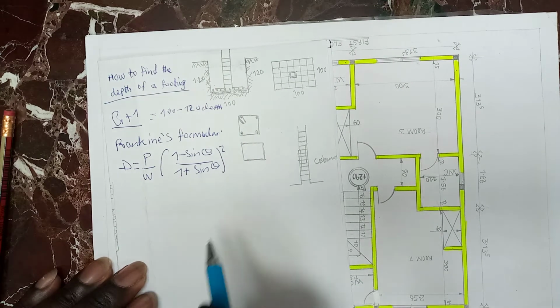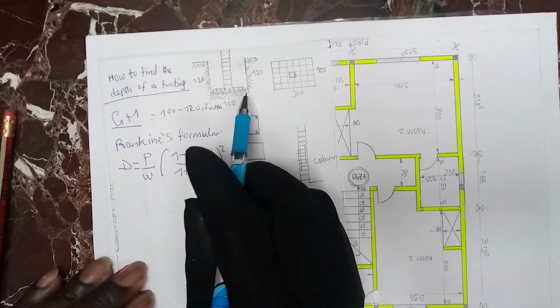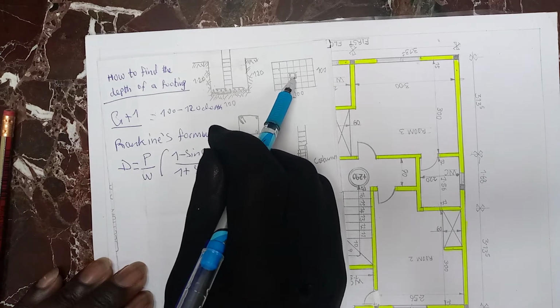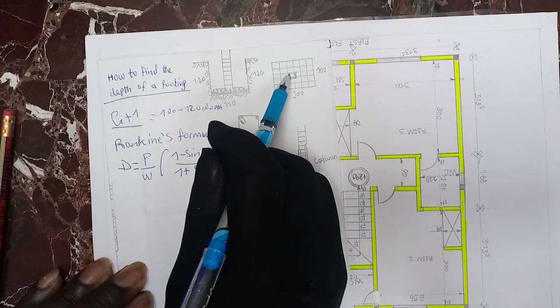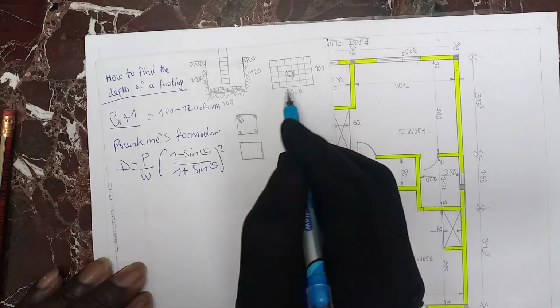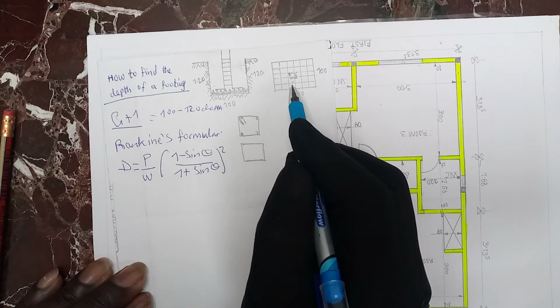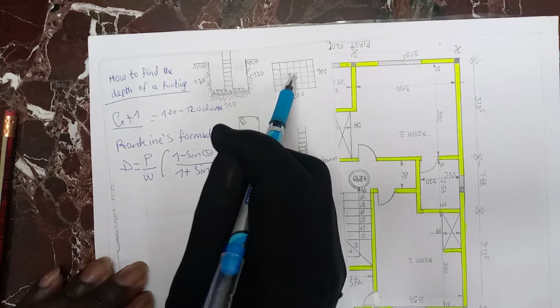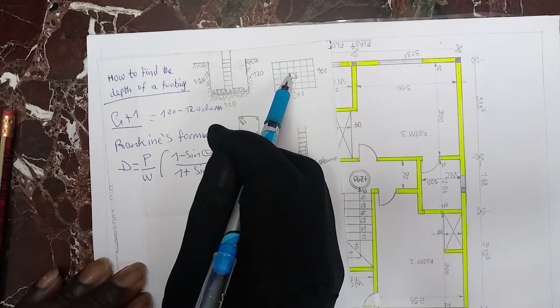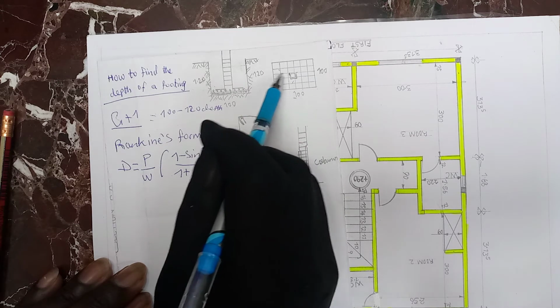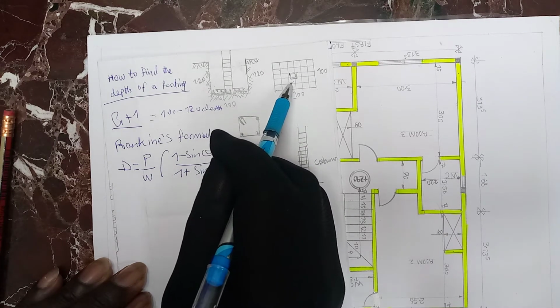But guys, this is our mesh. We consider this mesh down in our footing pit, and at the center you can see this is a column, a pillar, directly at the center. If this pillar is somewhere around this point, not at the center, it cannot carry the load, because the load comes directly at the center and has to be shared on this mesh.